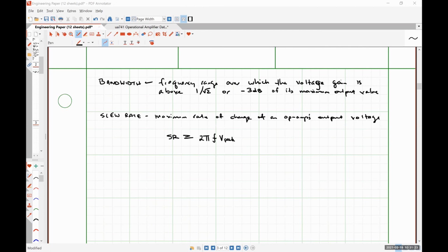Let's see, draw the equivalent circuit of this amplifier, assuming balanced input bias currents of 2 milliamps. So those would be pretty dang big input bias currents. So could you draw this with the current sources in there? I certainly hope so, because I drew it like 4 times. One between here and ground, one between here and ground, you're good to go.